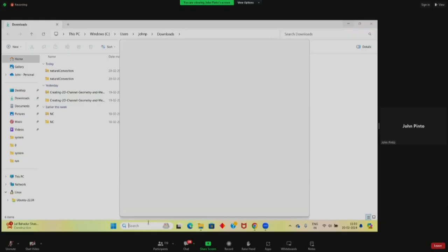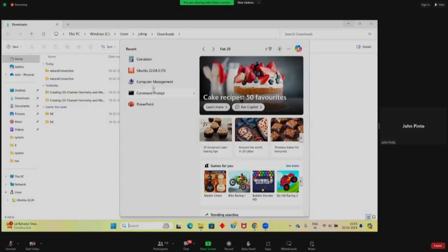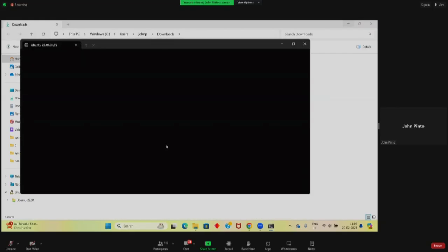Yeah. So the first thing you need to do is start your Ubuntu terminal, right? Go to start, search, and start your Ubuntu terminal. Wait for it; it will load. Now to go to your run directory, you can either type cd $FOAM_RUN or you can type just run. Run is a shortcut to go to that. So you type run and press enter. It goes to your run directory.